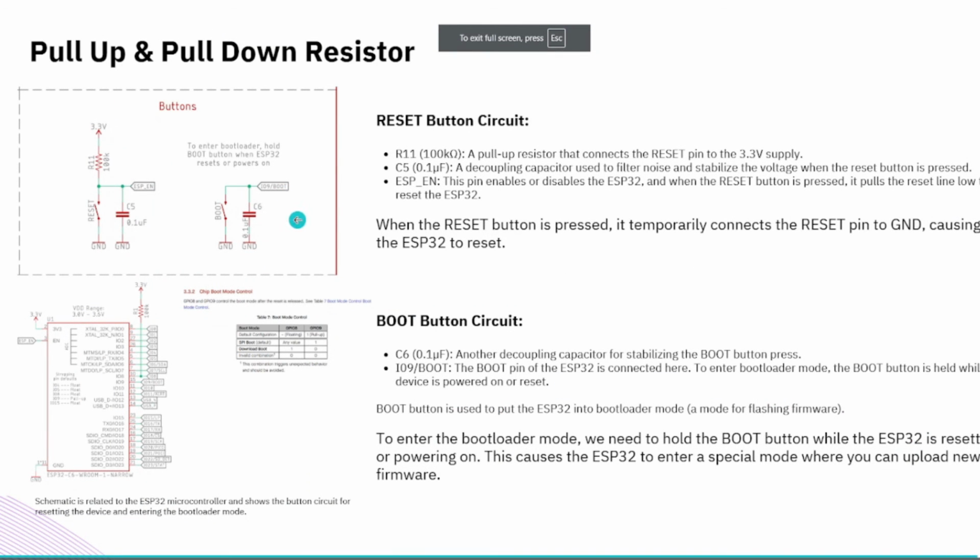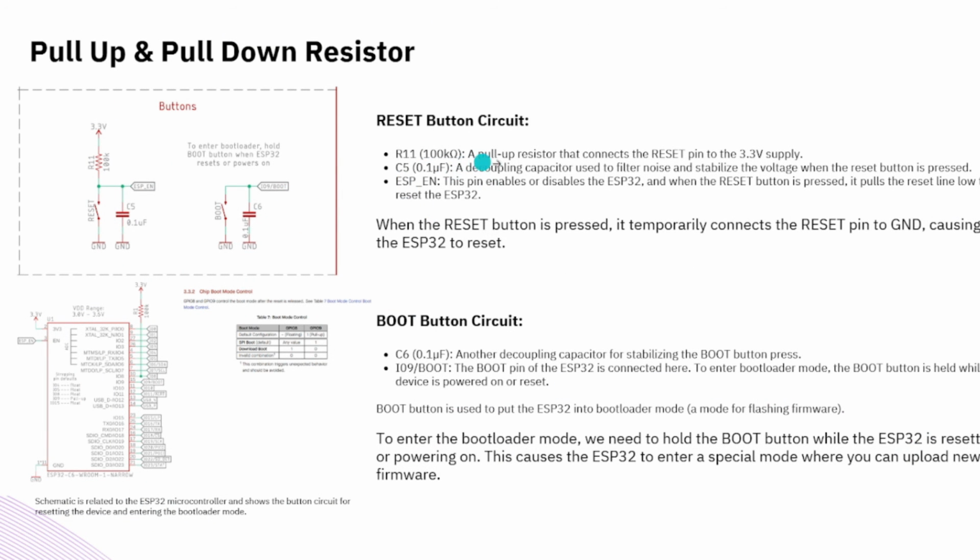We talked about this, and here you can see a pull-up resistor that connects the reset pin to 3.3 V, and whenever you press, you have this 0.1 microfarad as a decoupling capacitor used to filter noise and stabilize the voltage when the reset button is pressed. Similarly, the boot pin is there. One interesting fact you will see in the data sheet is that based on the state of the boot pin, the MCU can get into a download boot mode, or it can run through the default configuration when it is floating.